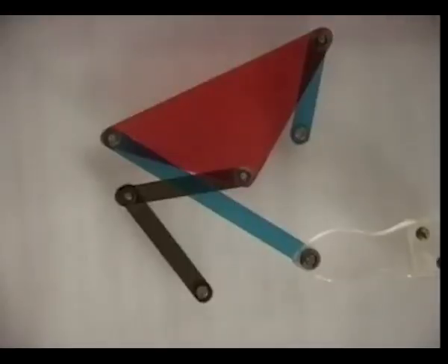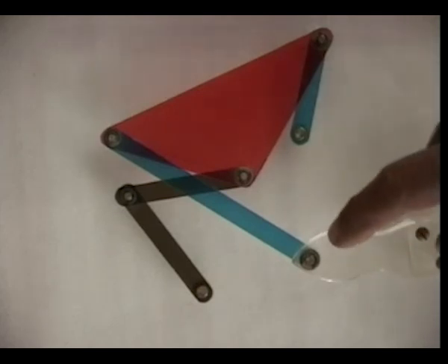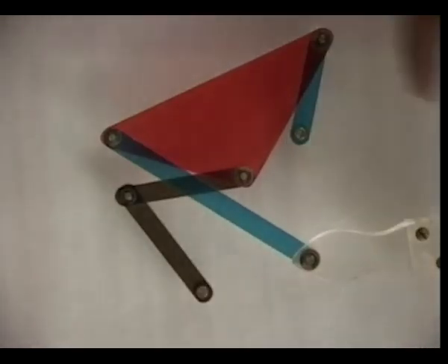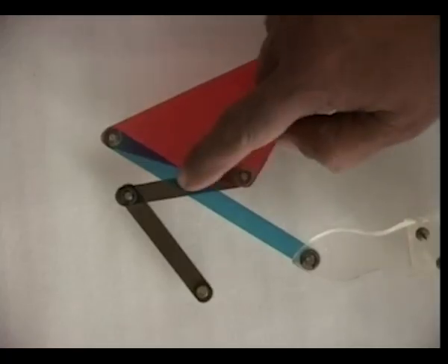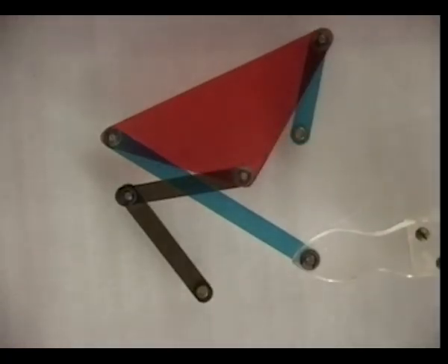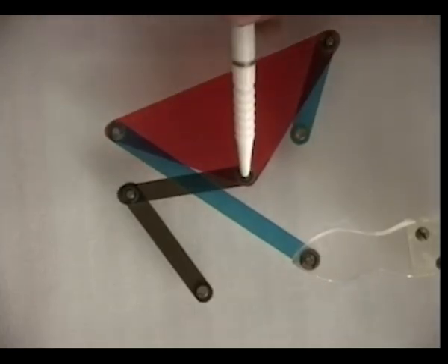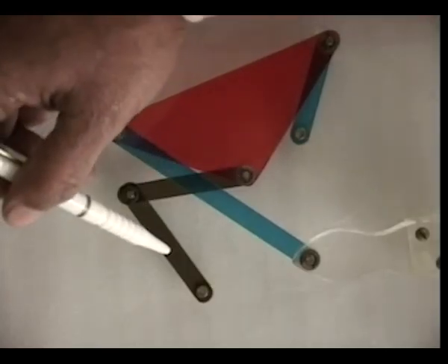Let us now look at the model of the Stephenson's mechanism where one of the ternary links is held fixed. Here we have this fixed link as the ternary link, which has three hinges, one here, one there, and another there. And this is the other ternary link which is connected to the fixed link by two binary links. So the two ternary links are not directly connected, they are connected via binary links at these 2 points and by two binary links at this point. This is a binary link, this is a binary link.